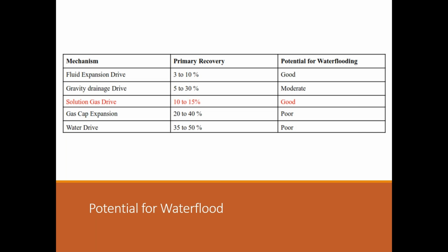The solution gas drive reservoir is a potential candidate for water flooding. It is good. And also the fluid expansion drive, both are ideal candidates for doing water flooding, or let's say water injection. In a water drive reservoir, since there is natural energy influx and water comes of its own, there is not much requirement. But in solution gas drive, there is definitely a requirement of pressure supplementation, and it is a good candidate.